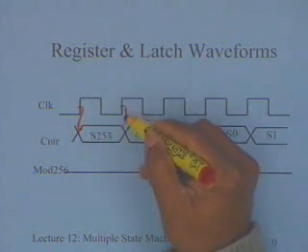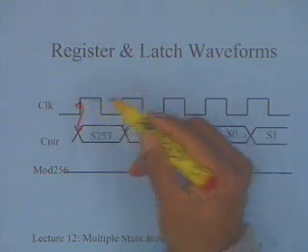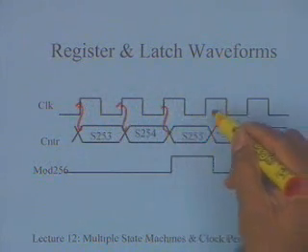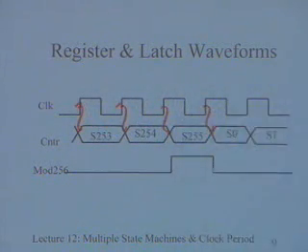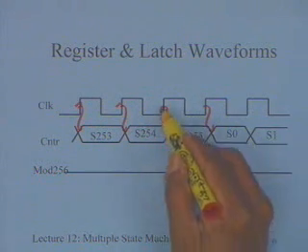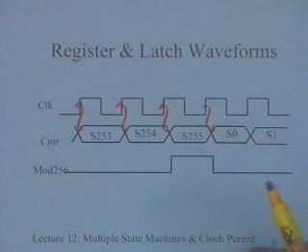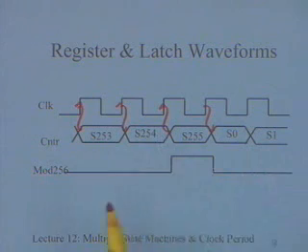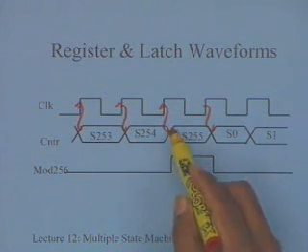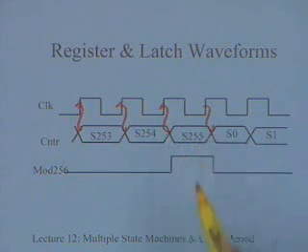follows this. It's all rising edge triggered, and the state change actually follows this. After this edge comes, after a small delay, which corresponds to the time that the counter takes, and we again have discussed various types of counters last time, the ripple counter and the synchronous counter. So assume that these are all synchronous counters, and so after a small delay the outputs will stabilize and we will get a state corresponding to whatever.